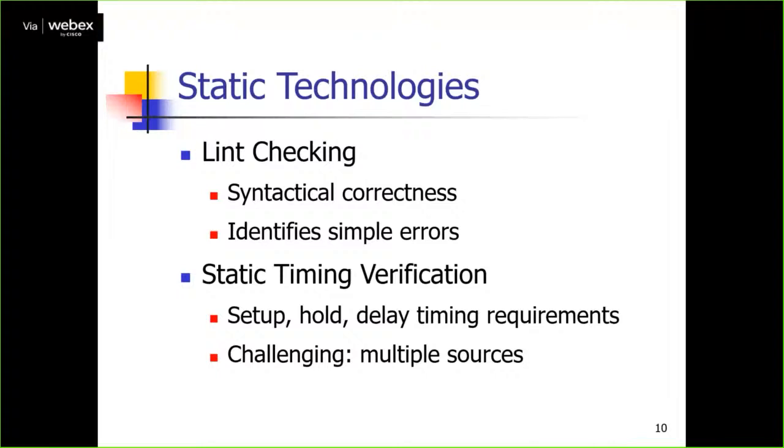Static timing verifications: we have different timing parameters to be verified. One is setup time, hold time, delay time, etc. Depending on the requirement, which is taken care of and can be presented, it goes with these setup, hold, and delay parameters. The major challenge in static timing verification is multiple sources. If you have n number of inputs, n number of peripherals, n number of outputs to be derived, then these multiple sources